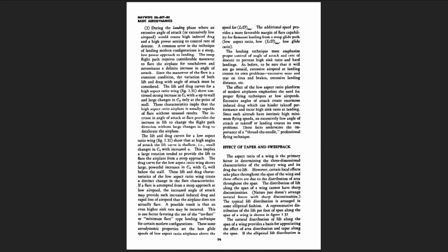These same aerodynamic properties set the best glide speeds of low aspect ratio airplanes above the speed for L/D max. The additional speed provides a more favorable margin of flare capability for flame-out landing from a steep glide path, low aspect ratio, low L/D max, low glide ratio. The landing technique must emphasize proper control of angle of attack and rate of descent to prevent high sink rates and hard landings. As before, to be sure that it will not go unsaid, excessive airspeed at landing creates its own problems: excessive wear and tear on tires and brakes, excessive landing distance, etc.